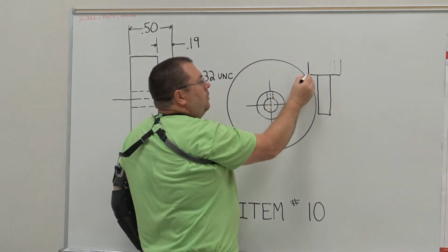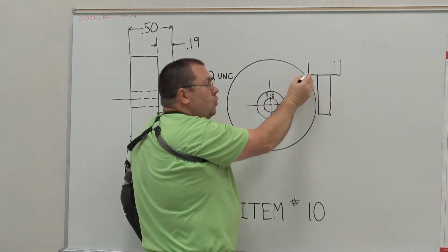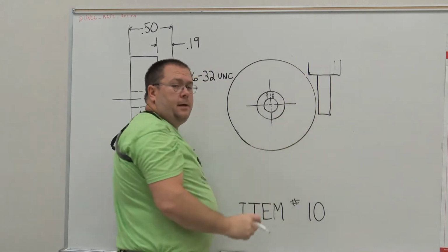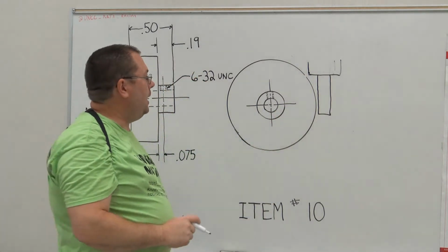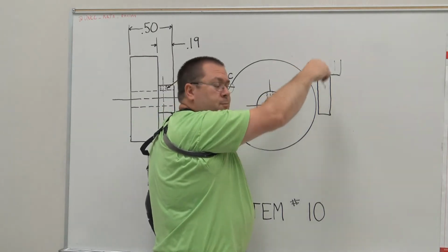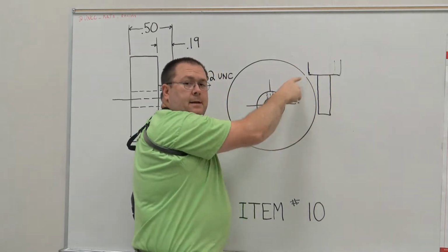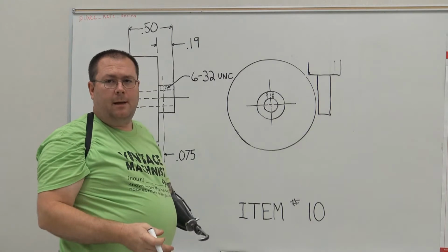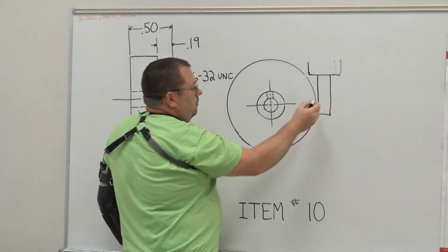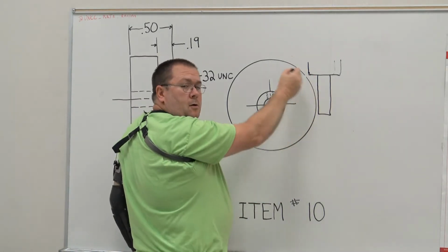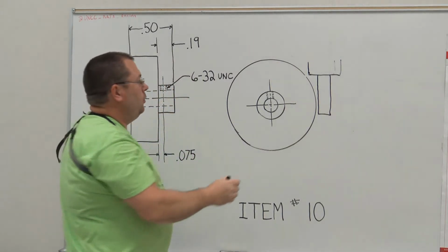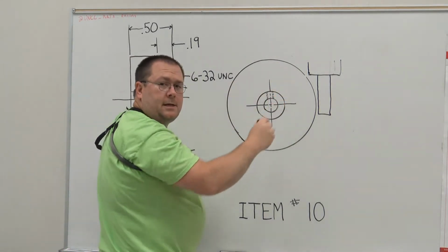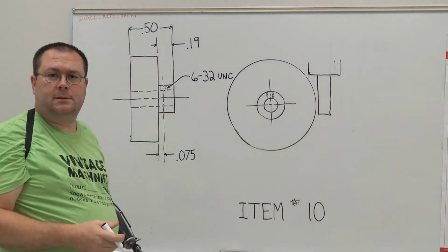Step number two, I want to make sure that this corner isn't what's hitting the 1 inch diameter. Okay? Because this thing's sitting there spinning. So if that corner hits that diameter, we've got a problem. Because if we hit somewhere up along above the equator, we have no real clue how big that cross section is. So we don't know how far we're going to step off.